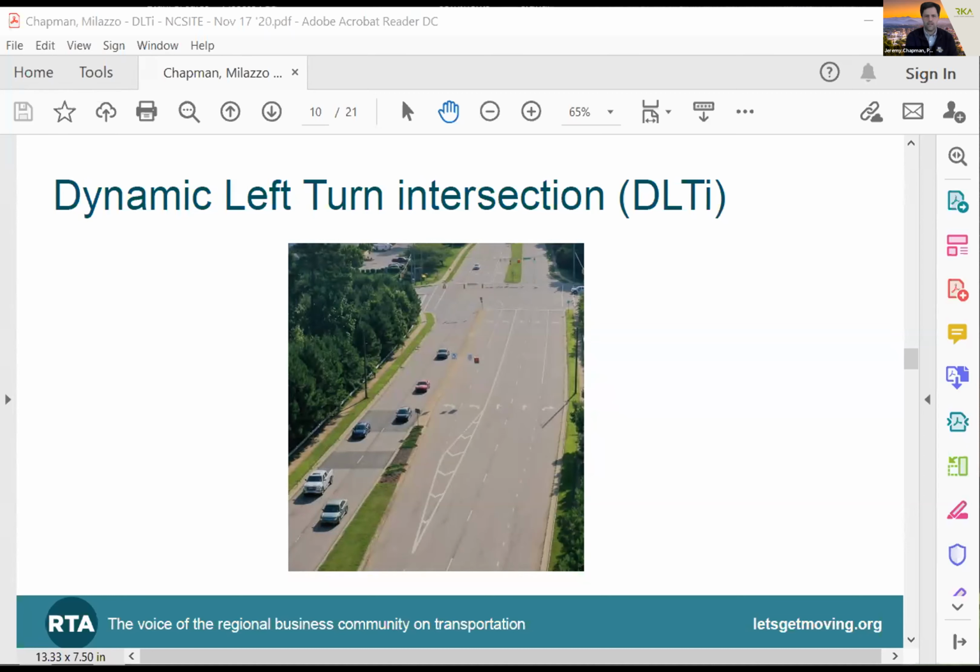So if they're in the left-hand lane, are they going to make that as a soft left rather than staying in their lane, going from inner lane to inner lane? Or are they going to drift across to the outer lane and make that turn? Also possibly an issue for turning radii for trucks. So those were all things that were considered and looked at.